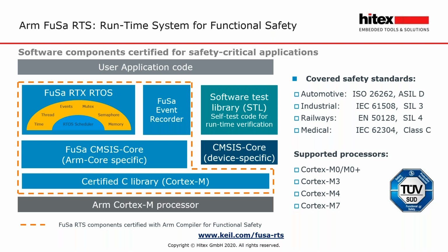As it is certified, it's possible to leave the Event Recorder agent inside your application so that during the early stages of prototyping and beta testing, you can have the functional safety code in there and still be able to pull out detailed diagnostic messages.